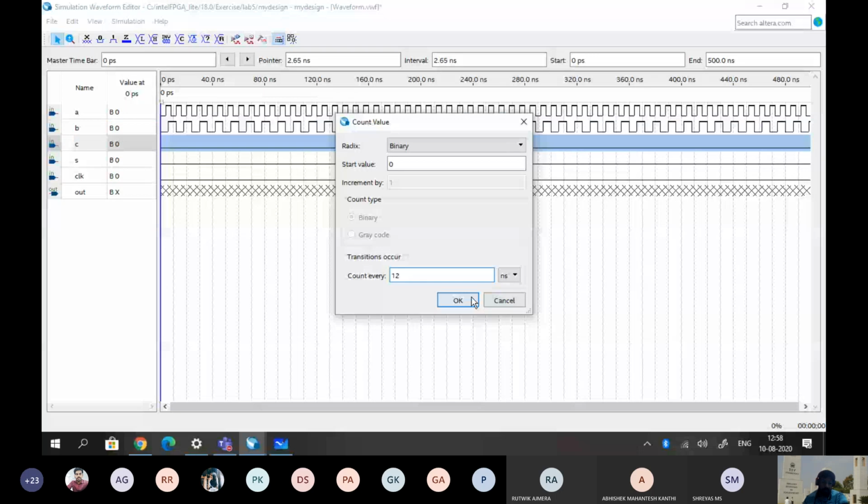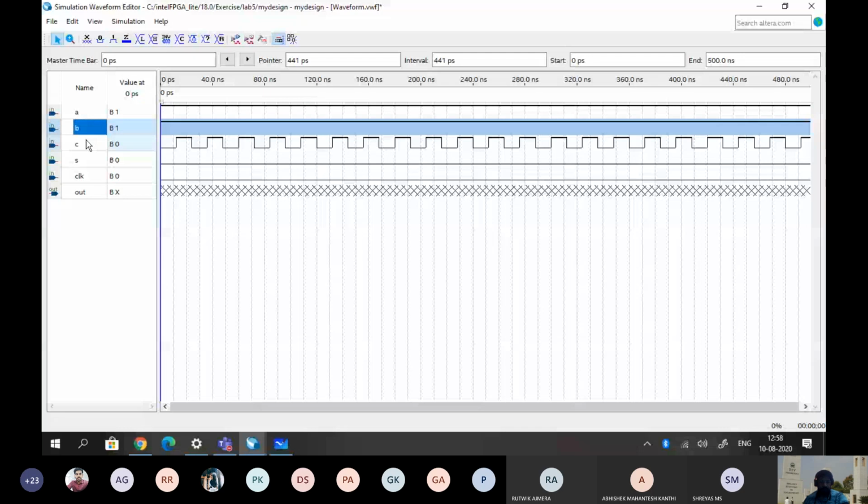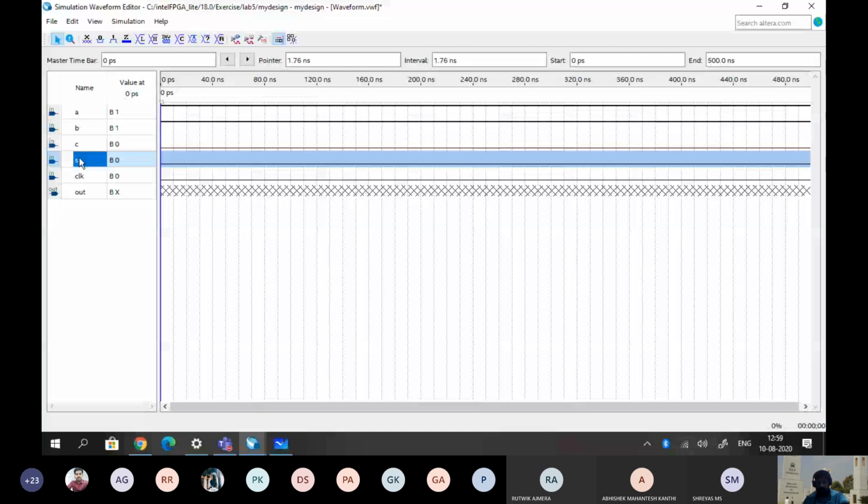So that you are able to see here the values like 0, 0, 0, 0, 1, 0, all those possible numbers. Or else manually you need to do it. Right now, for understanding purposes, I'm just keeping A high, B high throughout the simulation window, and C low. Now the selection line, and then I'm using the command every 100 nanoseconds, going high, low, so that I'm checking for logic 0 as well as logic 1.